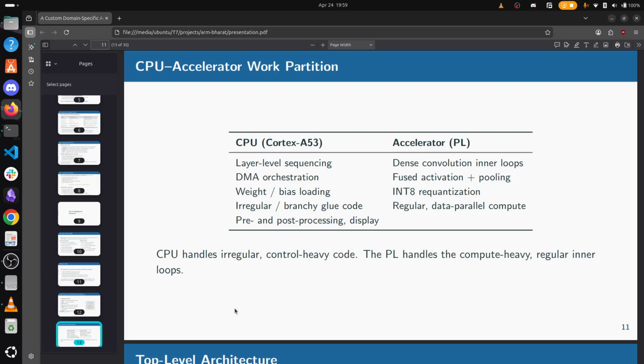We are not having any loops or conditional statements or branches. We are just having a set of multiplications and additions performed. So this is where the accelerator will shine, and it will compute all of this in parallel instead of doing one by one sequentially like a CPU does. It loads one instruction, executes it, then loads the next instruction, executes it. So this sequential thing can be avoided in our accelerator.